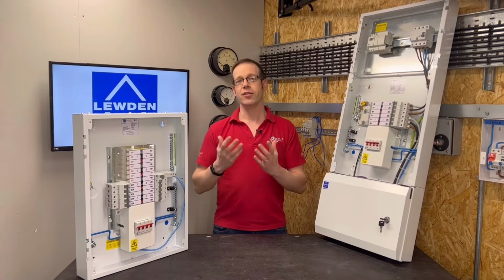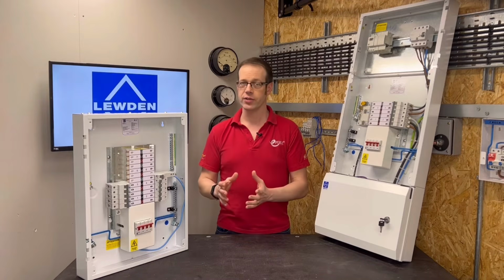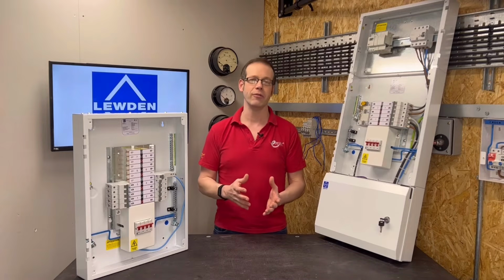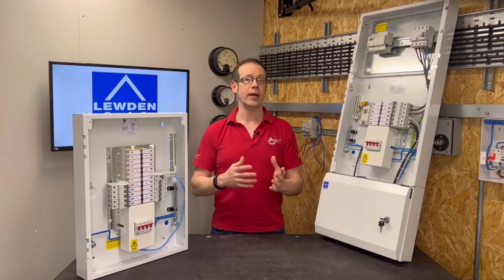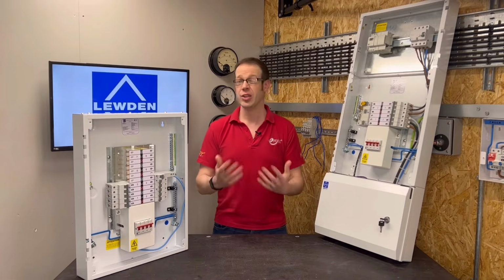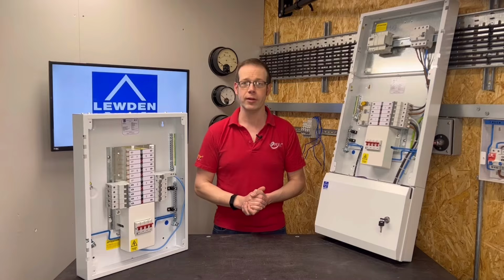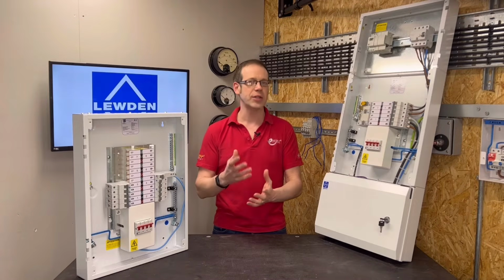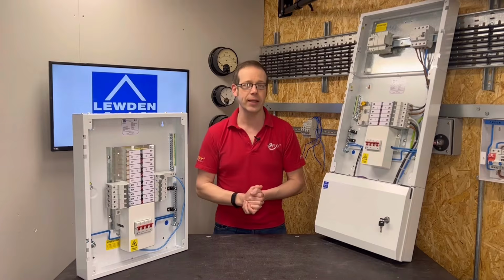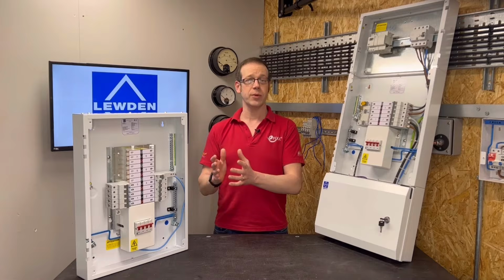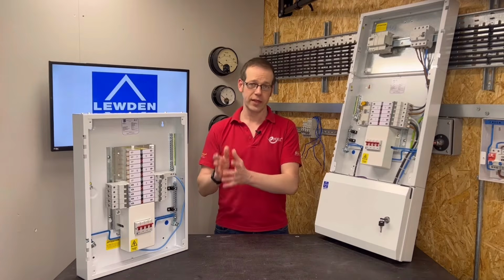The first is that three-phase can be used to drive motors. An induction motor can be built incredibly simply with very few parts that wear out and require maintenance. They can also be made relatively compact when compared to equivalent single-phase motors. This makes them cheap to buy and maintain and to operate reliably. For a long time, it was tricky to finely control their speed, which gave the edge to DC motors in certain applications, but the advent of variable frequency drives has ensured the three-phase motor has become the workhorse of industry.